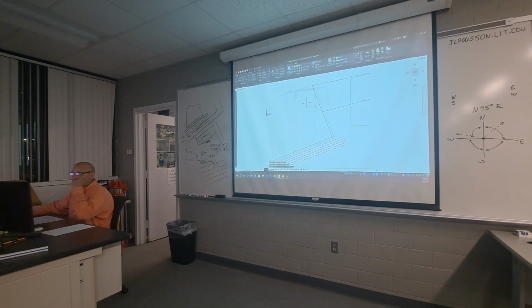If you had me for intermediate CAD, you already had this. AutoCAD says, do I wanna scale it? I'm gonna tell it no, which is the default, so I can just hit space bar. And bam, there's my football field in line with that property line. I can say, well, I need to move it off from my bleachers, my sidewalk, not a problem. My easement, got all that right here, plenty of room.